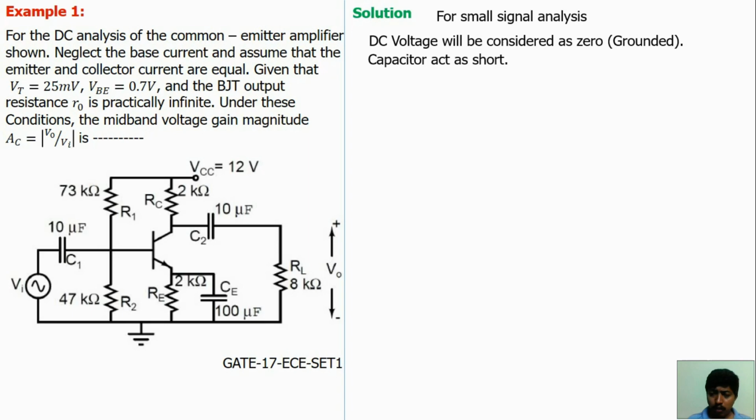Now, what is the equivalent circuit of BJT? This is the equivalent circuit of the BJT. Base, emitter, collector. In the base to emitter, there is a resistor. In the collector to emitter, it is a current controlled source, small ic. This is the equivalent of this BJT.